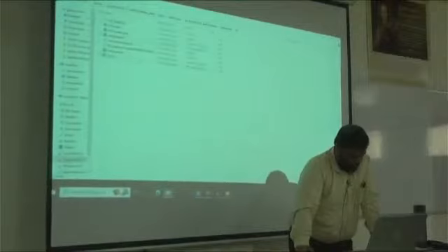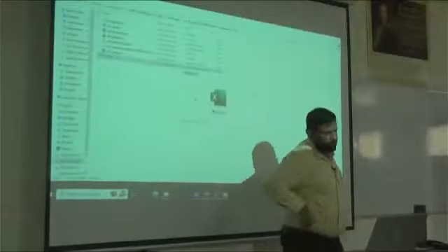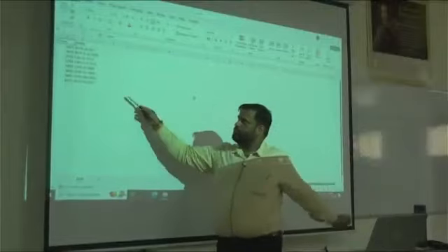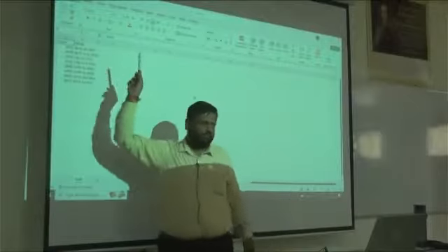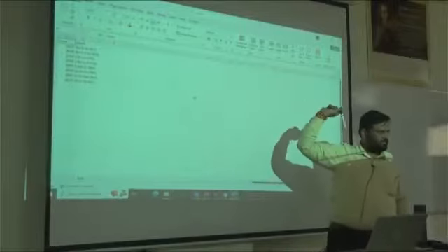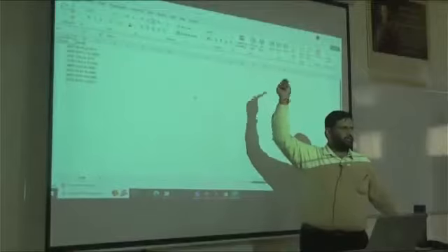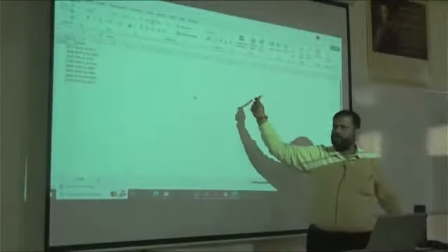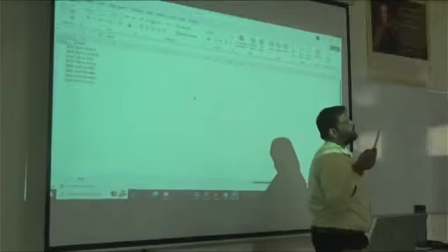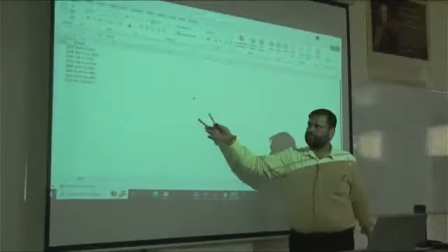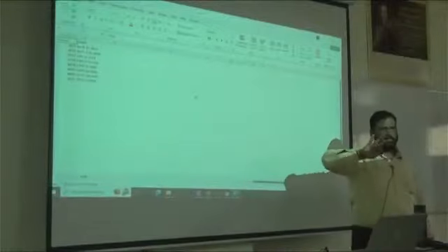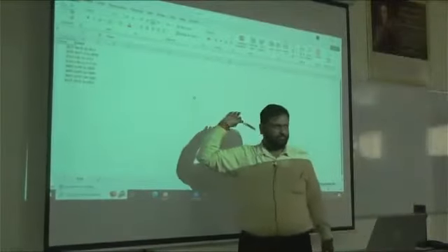So a raster format image is there. Along with that raster image you have to create one lookup table for the soil database also. So these are the codes which are being used in your soil database. Since I am using the FAO soil database, the FAO soil database is by default provided in your QSWAT reference database. If you are creating your own data sets, then you have to update your user soil file in your reference database. You have to copy all this data, whatever soil database you have created, into your reference database. Otherwise it won't be able to run the models.